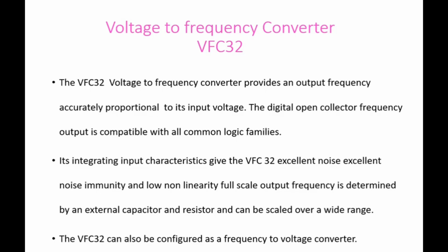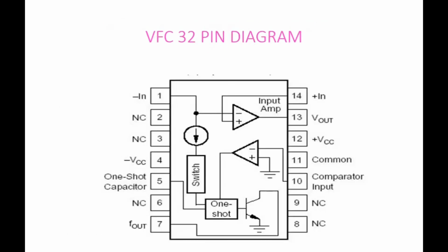and low non-linearity. Full scale output frequency is determined by an external capacitor and a resistor, and it is scaled over a wide range. VFC 32 can also be configured as a frequency to voltage converter.